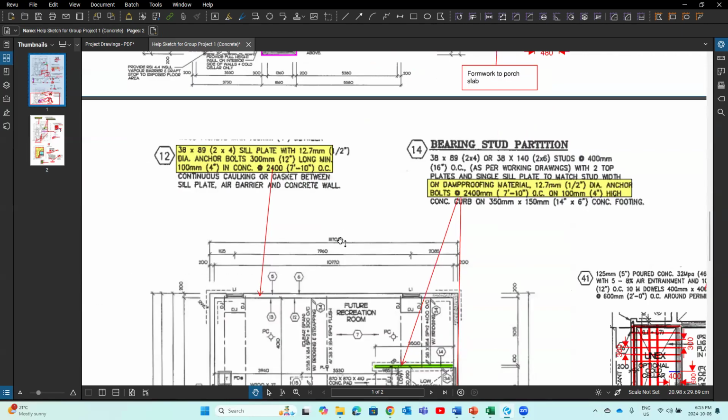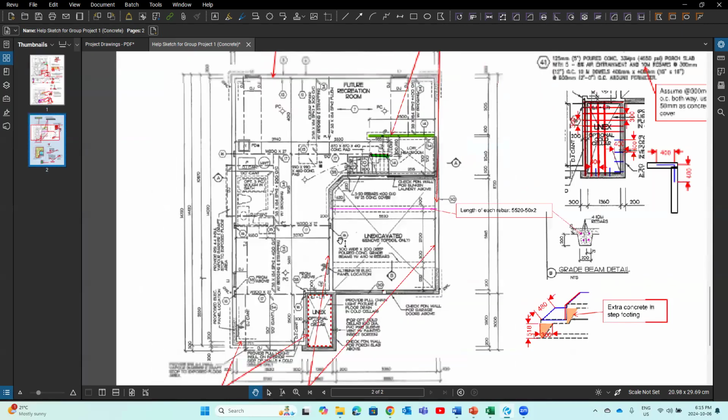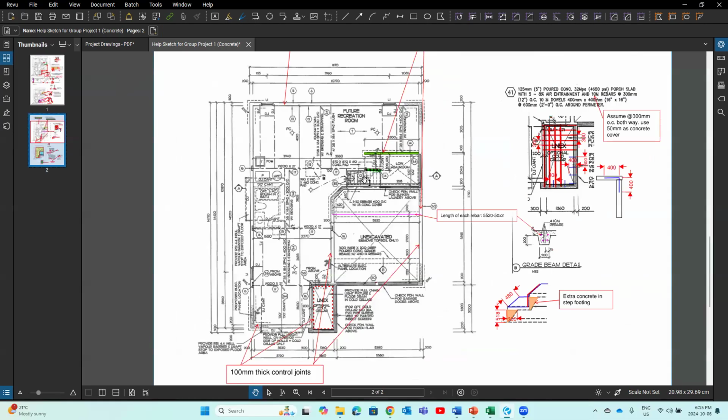So after we understand that, right, we would take the total length of this perimeter center line of the basement foundation wall plus the length of this wall. We do have that dimension when we calculate the formwork and concrete, right? So we take those lengths, add them together, add this length, right? And take that length divided by 2400 millimeter on center, we get how many?